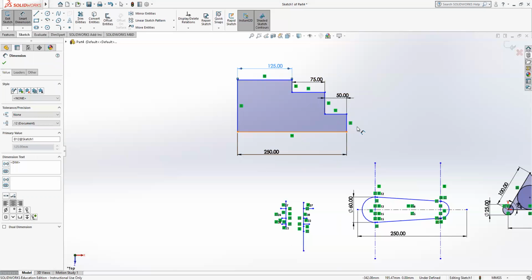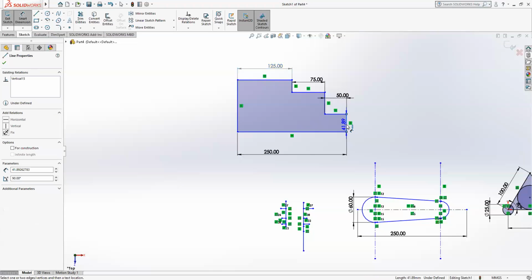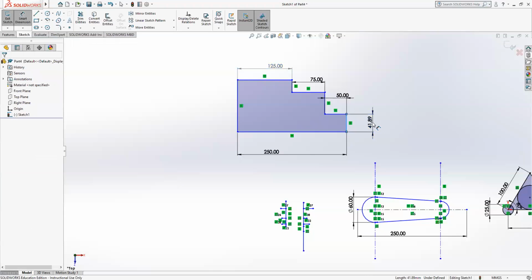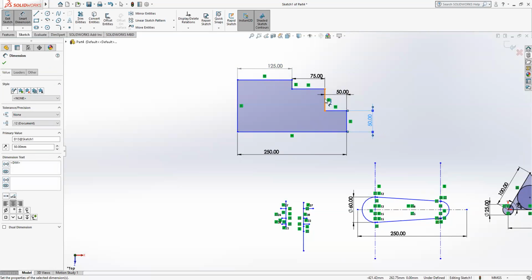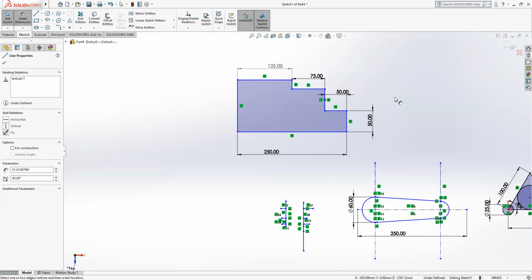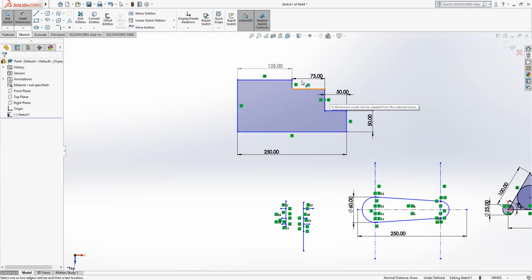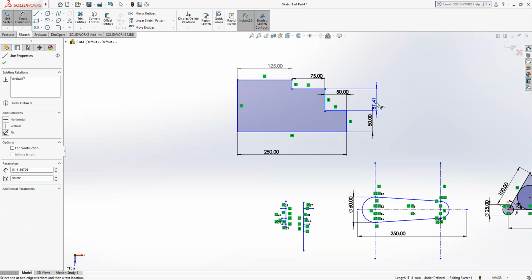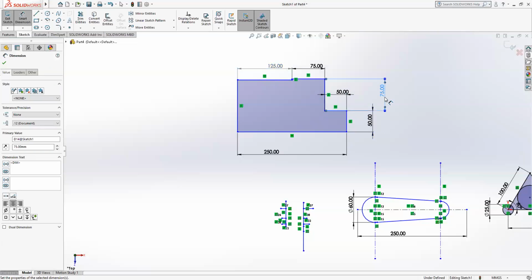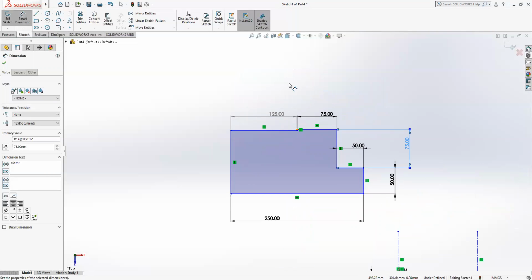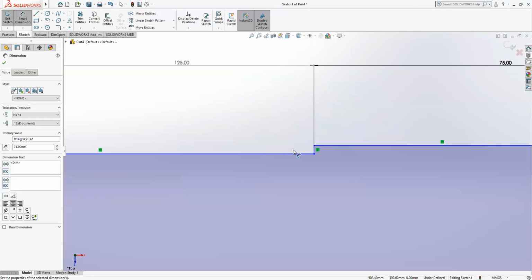And then we get the same thing if we're defining our dimensions on these. So let's make this one 50 as well. And we'll see it from the other direction if we come on now, Smart Dimensions. We'll make this one 75. And now you see that we have this little tiny line here that we're going to have to zoom in on.